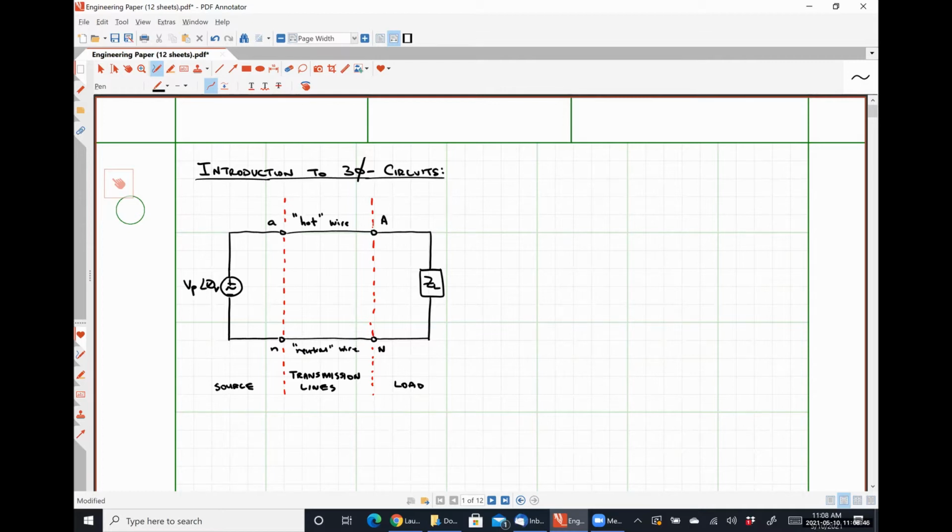So that's why there are 3 holes in the receptacles on the walls, okay? One is for the hot, one is for the neutral, and the little bitty one is the earth ground connection that ties to that. And that's just for protection purposes, which is why you can get adapters that don't have the earth ground connection. It will still work dangerously if you were to snip off the earth ground pin on your plug. You might burn something down, but it'll still run until it reaches an overcurrent state that earth ground connection was supposed to prevent.